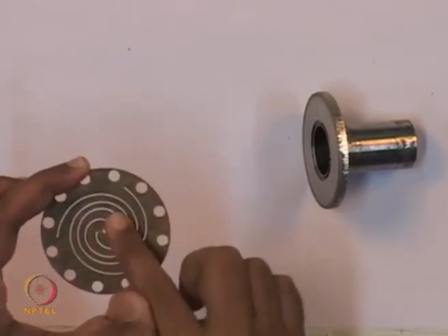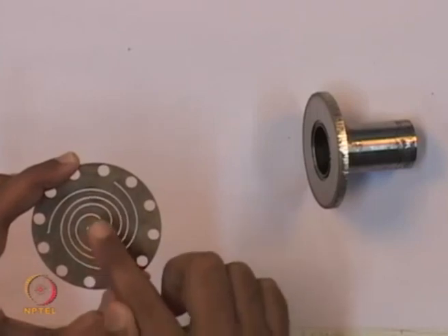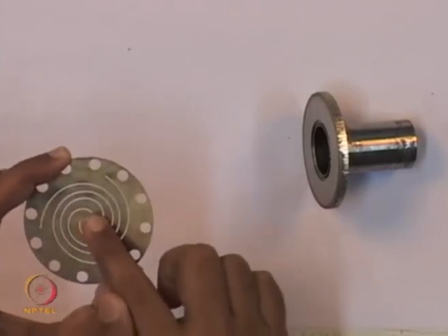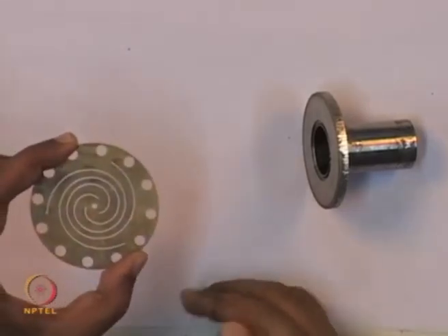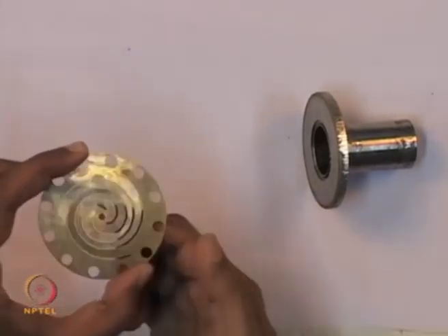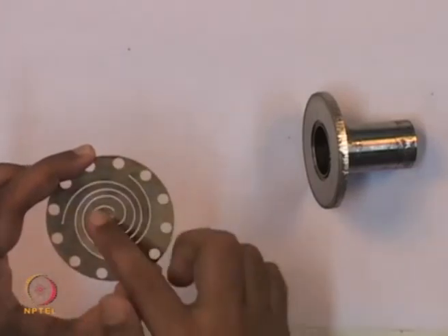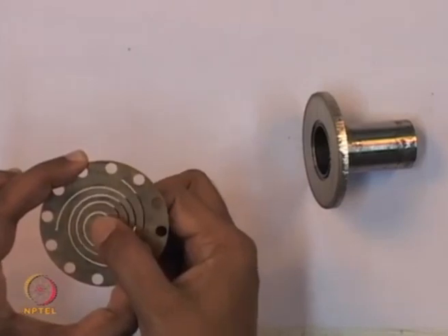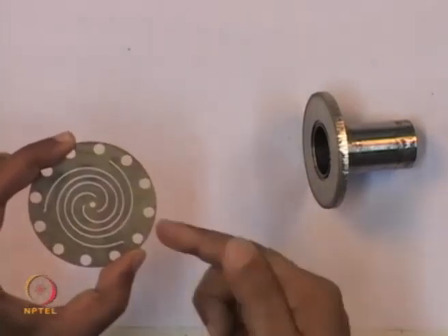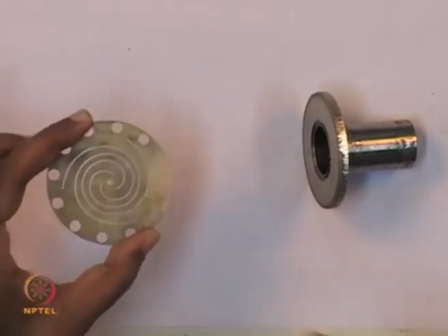So, while designing this flexure bearing, I have to ensure that the stress achieved while in motion is less than the fatigue strength of this material. This is very important: the bearing, which is subjected to fluctuating load, must be able to stand the stresses generated during this motion.